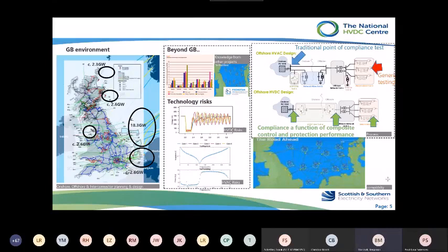The HVAC risk relates to small signal challenges associated with the resonances inherent in radial AC systems. And again, the inherent resonances within any current loop-based control system, and how they may combine, can disturb the onshore system, or indeed the vendor system of a large HVAC connected wind farm.